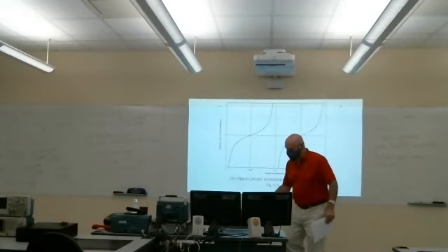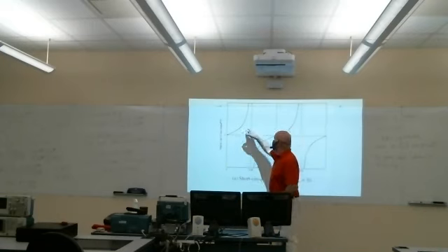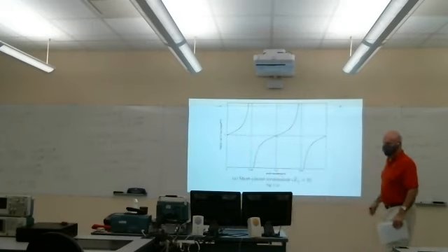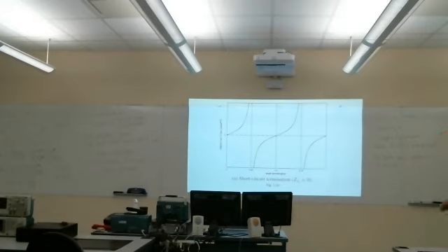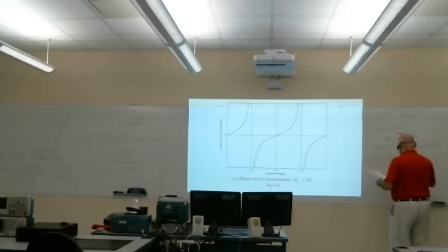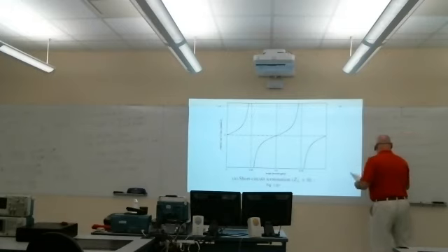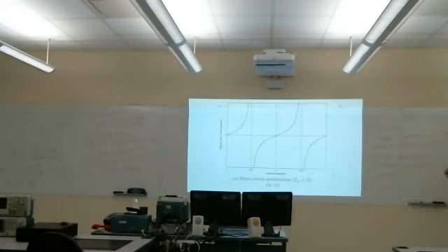So this is the previous figure. In this range, we've got this plus j thing, so it looks like an inductive reactance, and then in the next quarter wavelength segment it looks like a capacitor. So this short circuit transmission line can be used in place of an inductor or capacitor when building filters or doing impedance matching.